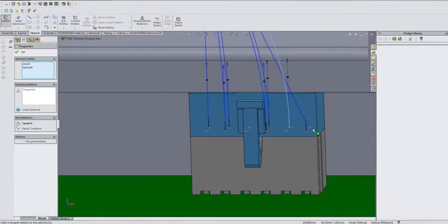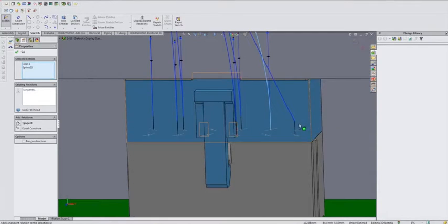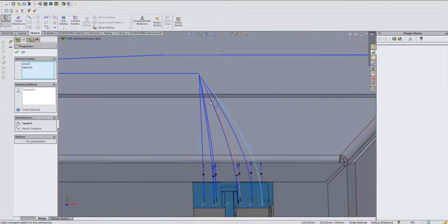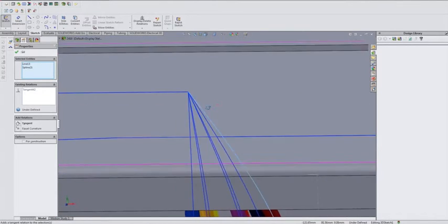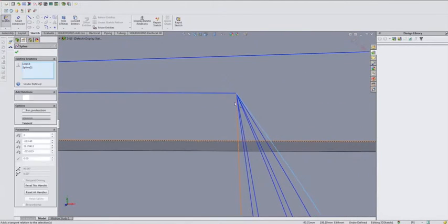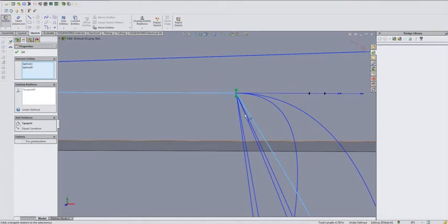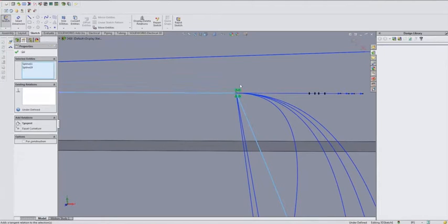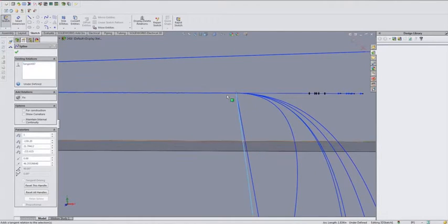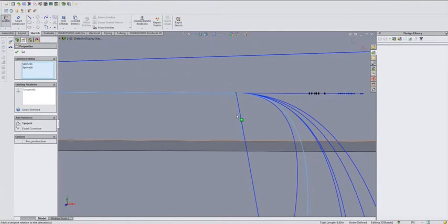So just adding in relations, and what that does is add a tangent relation between that stub as well as our route, and then the same thing here, right? This one's a little bit harder to do a window select because there's so many wires. So probably control select is best in this scenario. So what I'll do is I'll just do the first end. You kind of understand the process, right? It's going to be the same thing on the end as well.